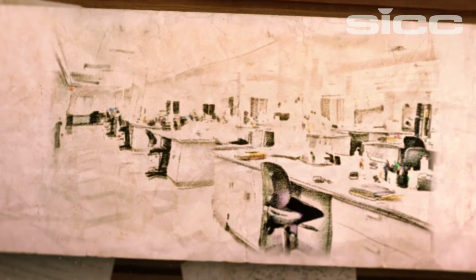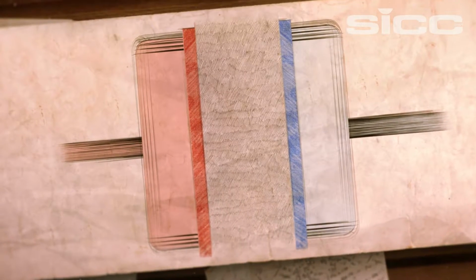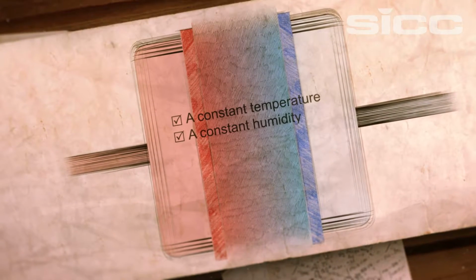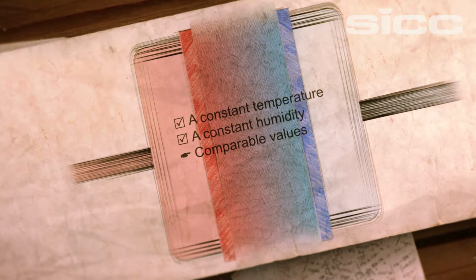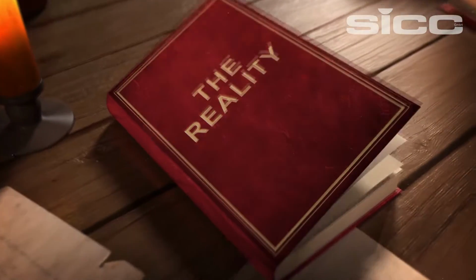In laboratories, the lambda value, as a building physics standard, is measured under steady conditions. In a so-called plate box, the heat flow is measured between a hot and a cold plate. And of course, circumstances such as temperature and humidity are steady in order to compare results. So much for theory and standard.